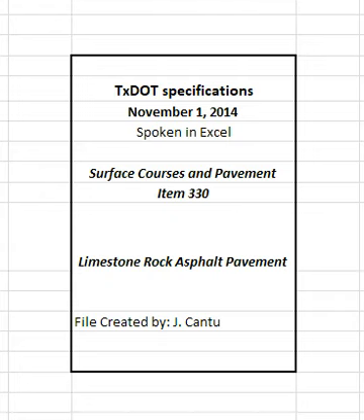When desired, dump the asphalt mixture in a windrow and then place it in the finishing machine with windrow pickup equipment unless otherwise shown on the plans. Prevent the windrow pickup equipment from contaminating the mixture. Defer compaction after placing the paving mixture as directed to allow for volatilization. Allow the previous pavement course to dry and cure before placing the next course when placing more than one course. The course will be considered cured if the hydrocarbon volatile content of the mixture is 0.4% or less by weight of the mixture when tested according to TxDOT 213F, unless otherwise directed.